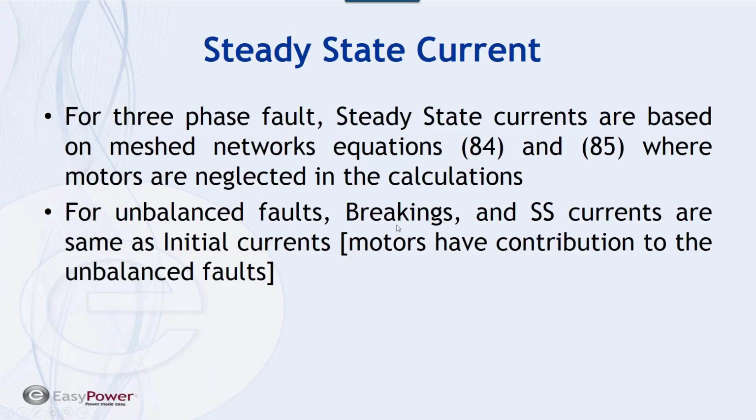I go back to that statement again. For unbalanced faults, breaking and steady state currents are the same as initial currents, which we just saw, that motors have a contribution to the unbalanced faults, and that is true.